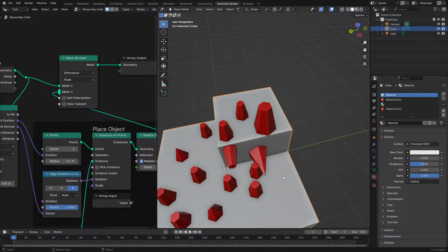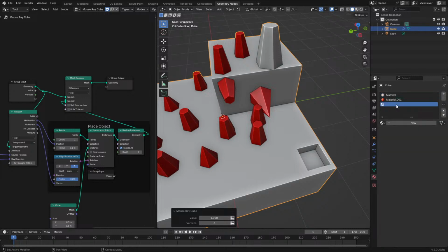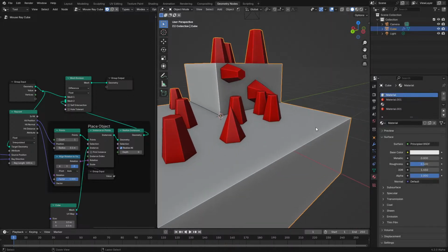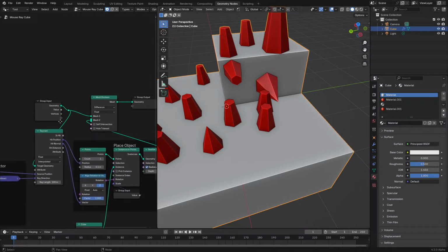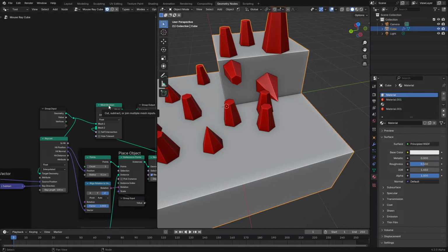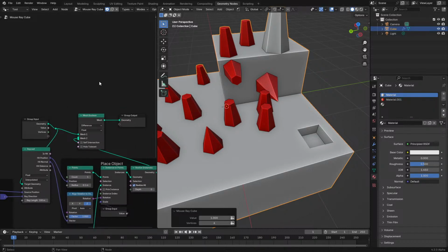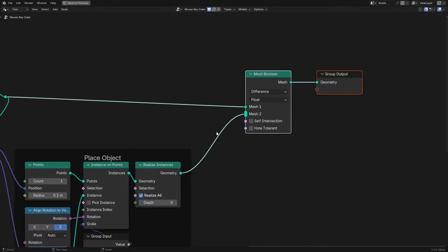So one thing that happens in Blender 4.2 is that when you add an object without a material, it basically creates an empty material right here, an empty material slot at least. Which makes a bit more sense, but makes some previous workarounds for transferring a material from one object to another not viable anymore, which is unfortunate. We really need a sample material node from a mesh, because right now there's not really a way of transferring the material from this object to that one. Well, no, there is a way of doing it, but it won't make it so that it's fully eliminated. Actually, no, I will try that, just to make sure that I'm accurate in my assessment.